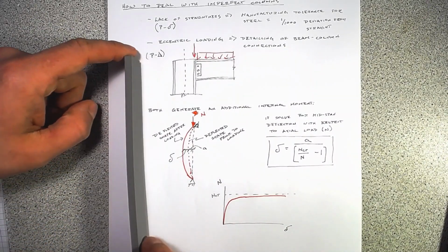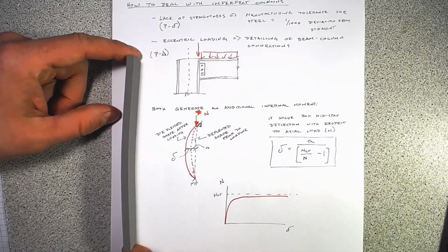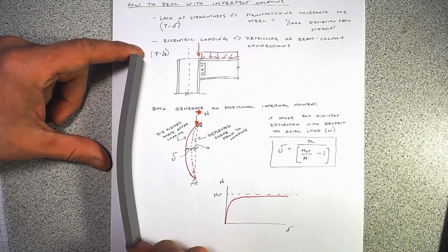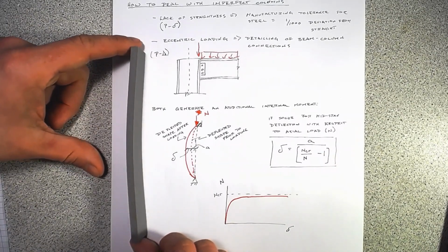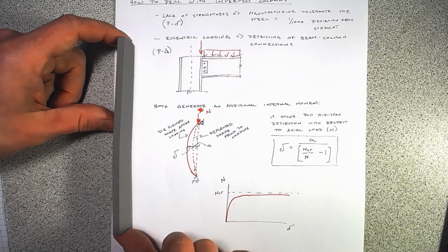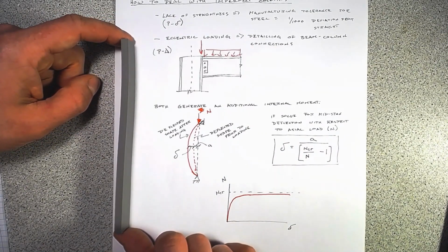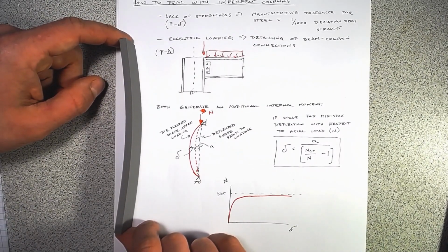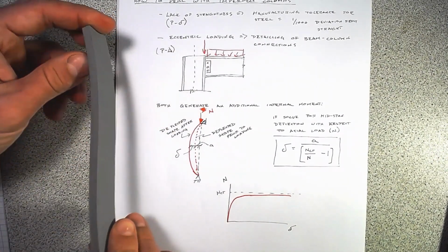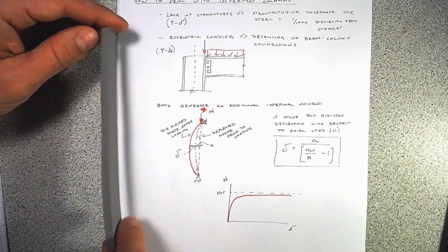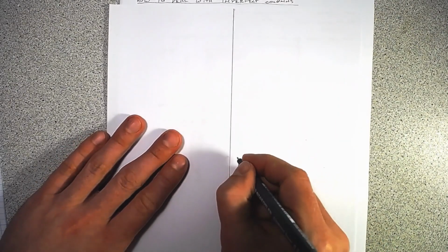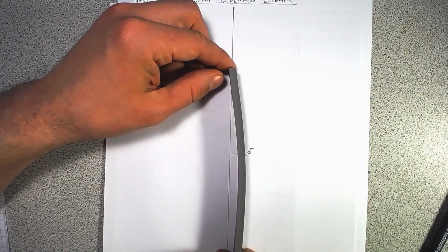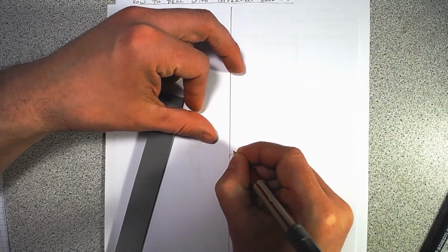So say we start with our little column here. If this is initially straight, and as I buckle, you can see it goes really quick. I'm putting very little load on here, but it goes really quick, and that's this deformation increasing. So if it's nominally straight, push, push, push, and then it kicks out. If we have some initial out of straightness, see just this little bit here, I push, and then you can see that it will move rapidly, this out of plane deformation here. So if we take our little line, this way is delta. So we'll put our little A in here.